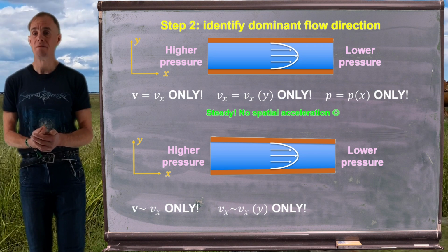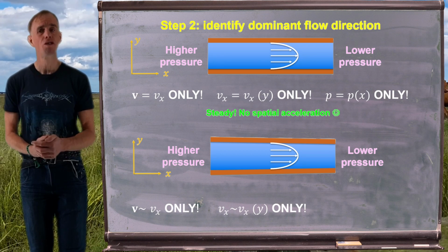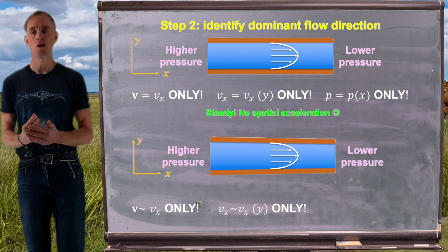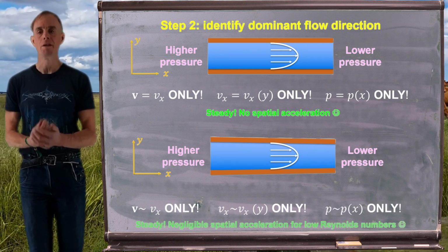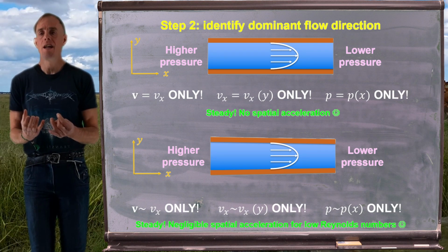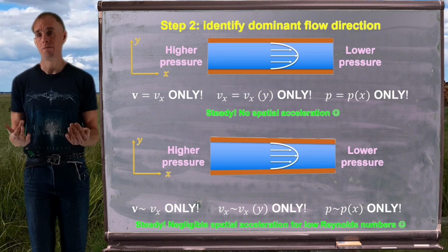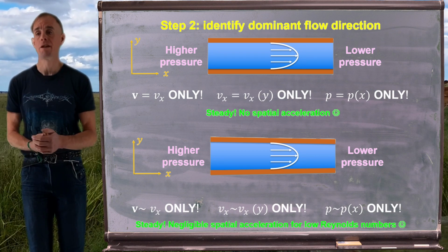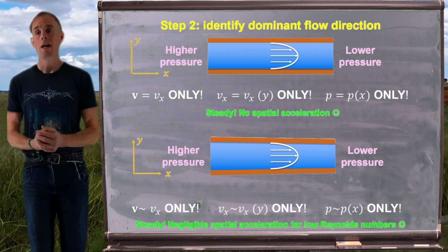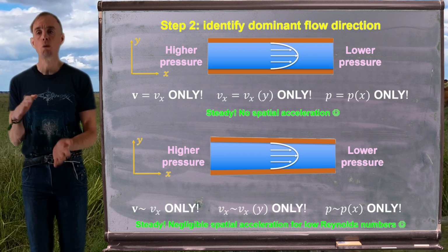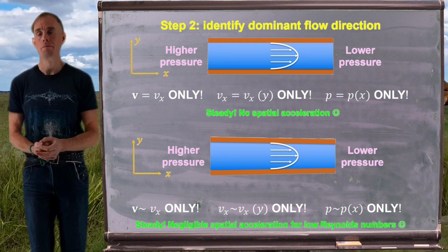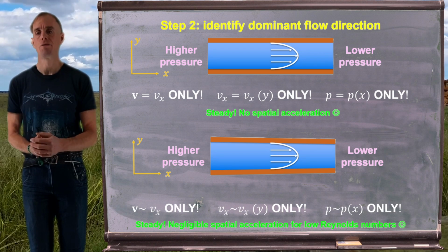And again, you can make some arguments as to whether you might have a very mild transverse pressure gradient, but we've only got one dominant pressure gradient, and that is in the flow direction, in the x direction. And so we can say here that really you've got negligible acceleration. So we're just going to look at the dominant flow directions, and it's effectively the same problem as we're solving at the top diagram. It's just we might want to describe how our walls change as a function of length in a slightly more detailed way. But we'll not worry about that just for now.